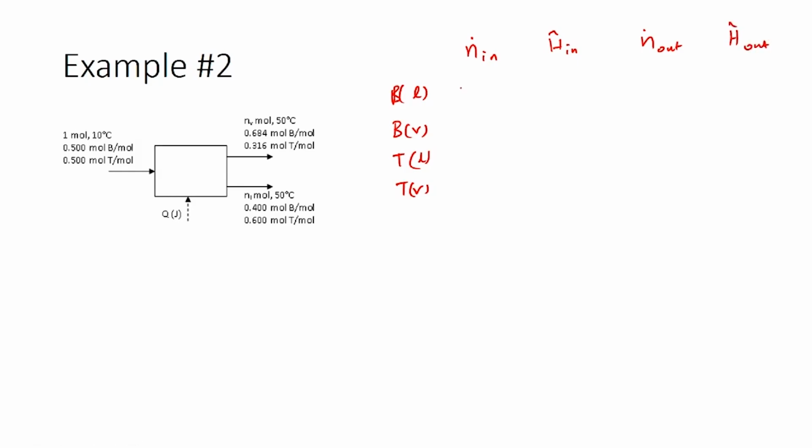So, when we fill the table, it will be 0.5, 0.5, and you do not have anything coming in here, and these values would be 0 because of the reference states, and you have 0.259 moles of benzene liquid leaving the system and 0.241 moles of benzene vapor leaving the system. Toluene liquid is leaving the system as 0.389 moles and toluene vapor is 0.111 moles leaving the system.